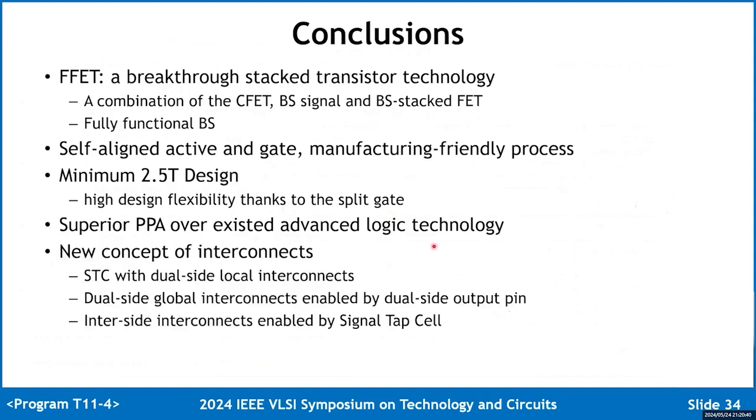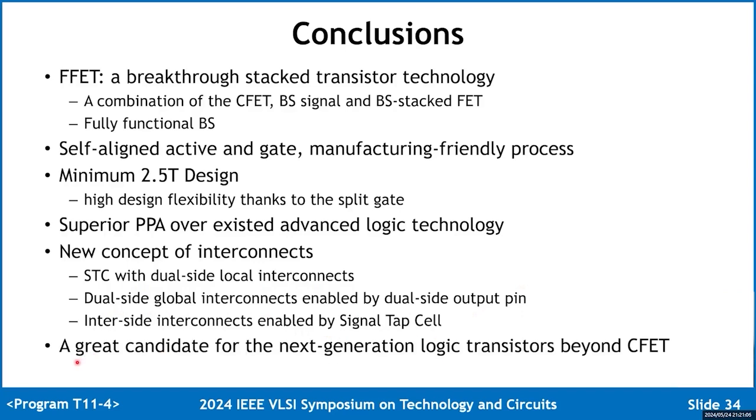We propose some new concepts of interconnects. First, the FFET standard cell is designed with dual-side local interconnects. Second, dual-side global interconnects enabled by dual-side output pin is proved workable by doing placement and routing. Third, inter-side interconnects is enabled by the signal tap cell. We believe that the FFET is a great candidate for the next generation logic transistors beyond the CFET.